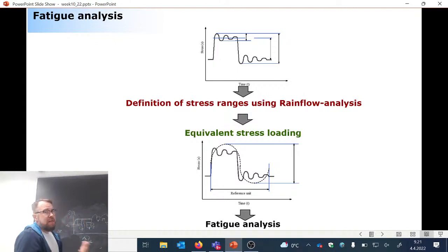So now you've got the collection of deltas. Based on this collection of deltas, you make statistics. There are different sizes of deltas. Let me put it in a simple table here. Delta, let's say, 100 megapascal. You count, okay, there are 10 times like that. Let's say 3 times like that. And then a delta smaller than that, let's say 90 megapascal.